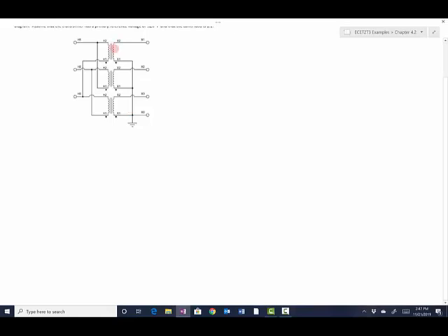And each of the individual transformers is, of course, labeled according to the American Standard Transformer Notation, where we've got two terminals labeled H1 and H2 on the primary, and two terminals on the secondary labeled X1 and X2. And on all of them, they're labeled with the dot convention. Just remember that if current flows into the dot, it will induce a voltage that is positive at the corresponding dot on the secondary side. So that's what that means, and that will be important for this.